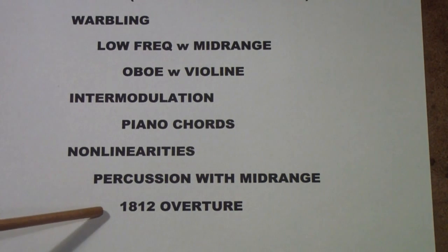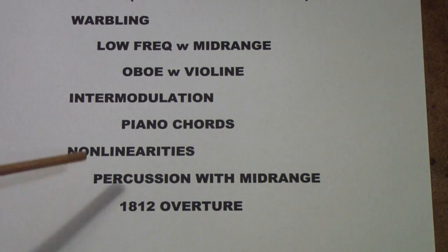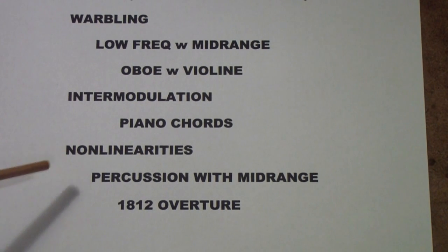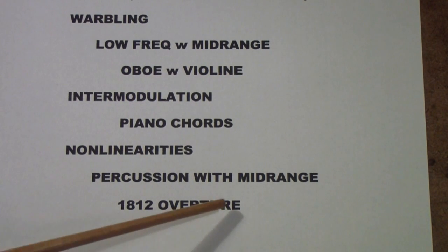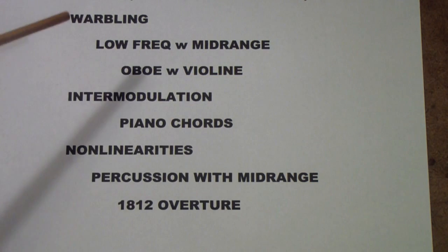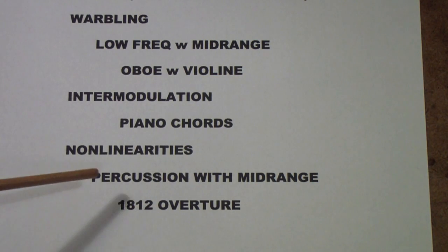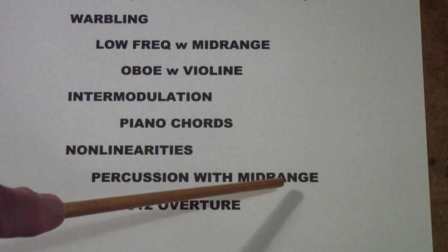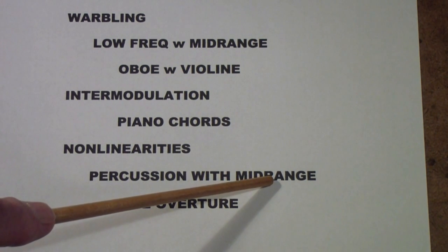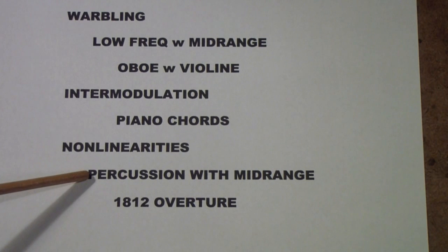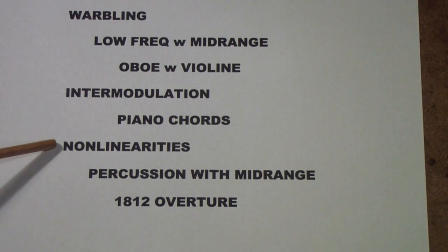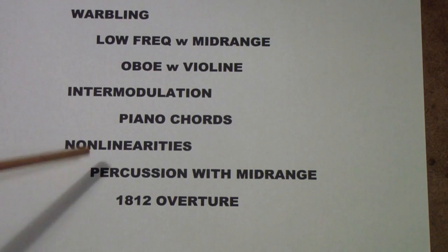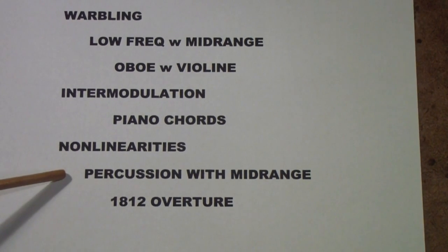Listen to those, and I think what you will see is if you have a nonlinear amplifier, that is an amplifier that generates intermod or harmonic distortion at higher levels, what happens is even though you listen to the mid-range at low volume, when the percussion comes in, it drives your amplifier into that nonlinear range. Now you can test this to some extent electronically.